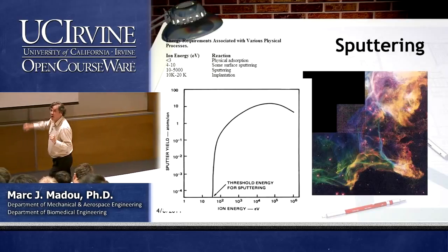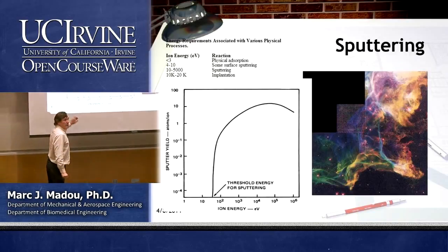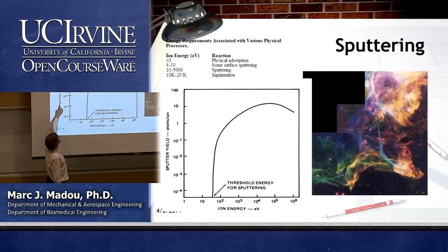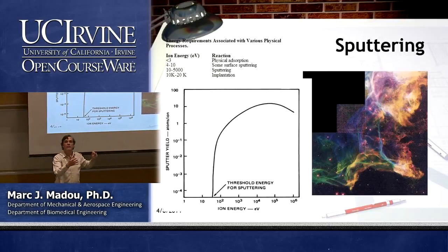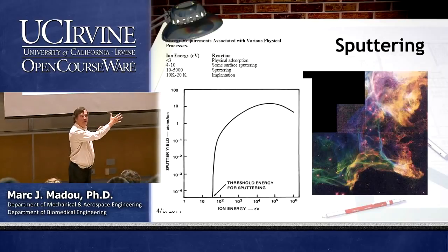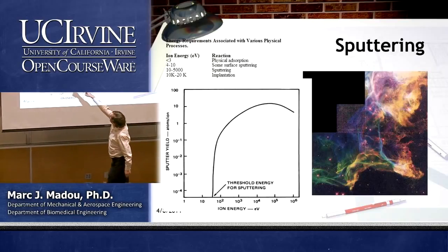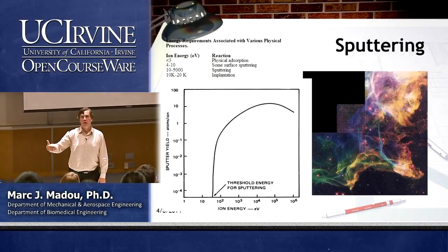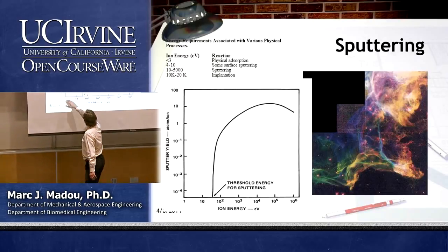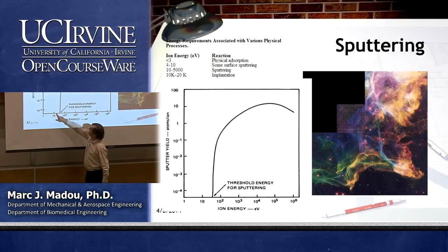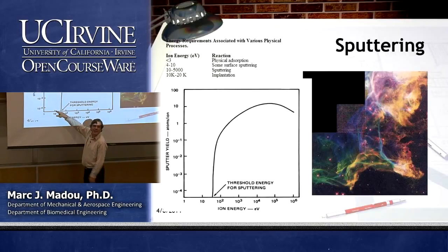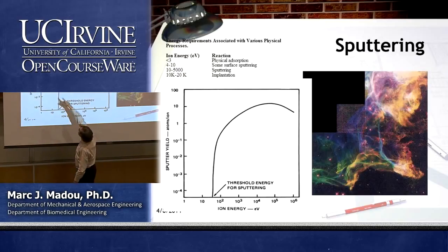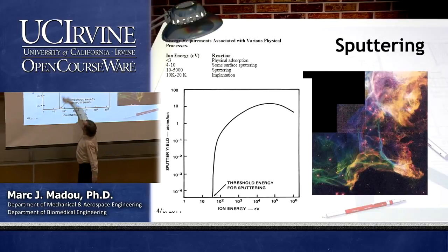This curve here, since I still have a bit more time, in a way follows up on these 4 items. Here it shows sputter yield. That means number of atoms I kick off per ion that comes in. So yield, for example, if I have 1, that means each ion that comes in kicks off 1 atom from your workpiece. And this axis is the ion energy. So you guys already know, if it's less than 10, I'm not kicking off any atoms. I might be sputter clean.